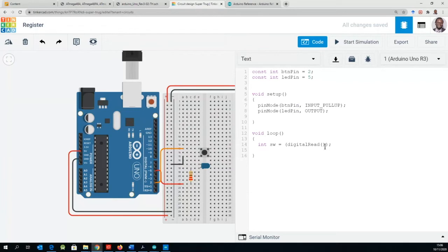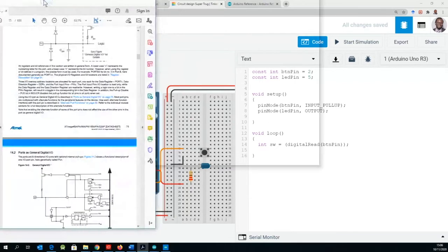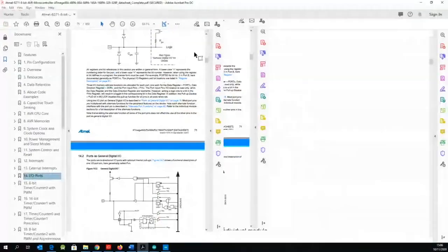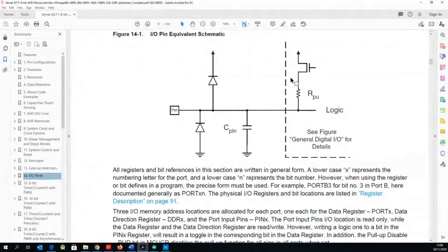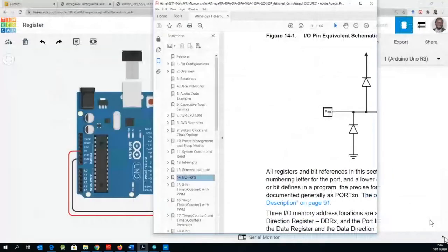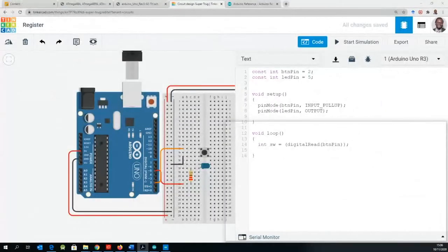Remember, because we are connecting to the pull up as we showed earlier, now all we've done is just to connect this to the 5-volt source on pin 5. That's what we've done. So move this on the side. There's some room. Back up.